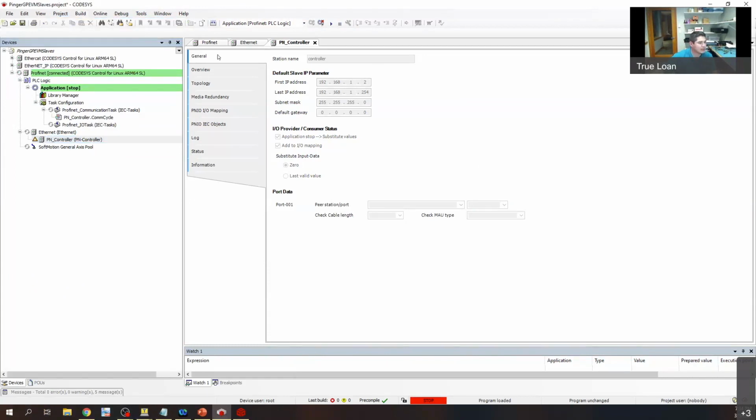And so when I kick off and log in, that application binary is deployed automatically, and then we're left in like a breakpoint state. See, I have to hit play here for things to actually happen. And once I hit that play button, now I can see that my Profinet network, my Profinet controller stack is actually running, and that's symbolized by this orange spinning wheel. The orange is indicating here that I have a trial license. I don't have a full license on this AM64 development kit, but you could go ahead and pay for that and actually deploy the system in production if you'd like to. Right now, this will just kind of expire after some trial period, maybe like an hour.